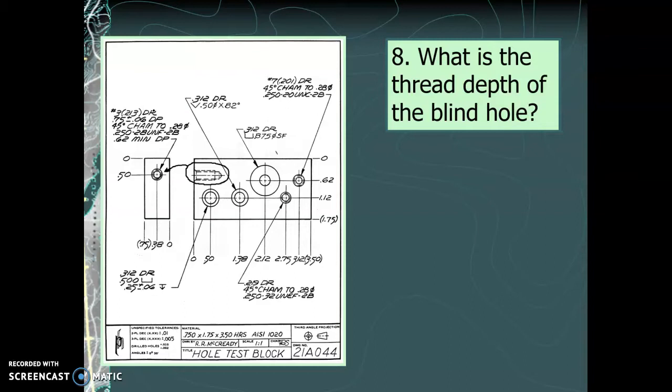So that's the drill that's used for the hole. 0.75 plus or minus 0.06 depth. So that's a depth, but that's the depth of the hole itself. In addition, the hole has a 45-degree chamfer, and the chamfer is made until the outside chamfer diameter, the outside circle there shown with a continuous visible line, has a diameter of 0.28.